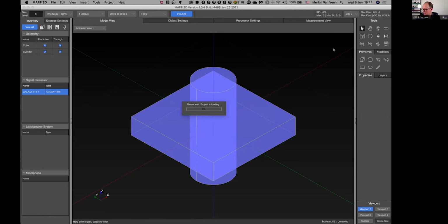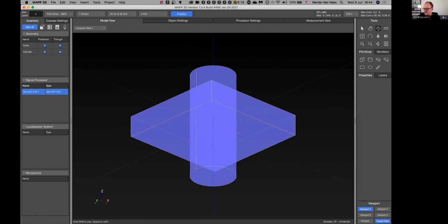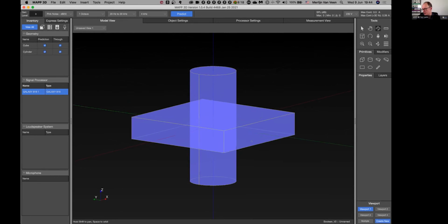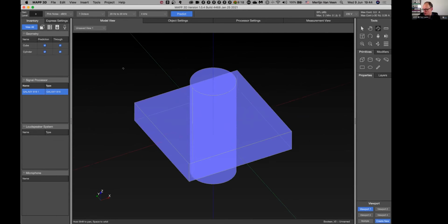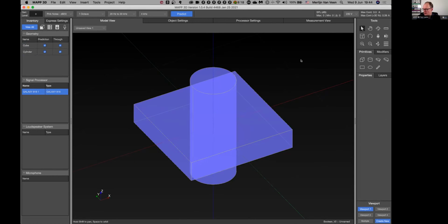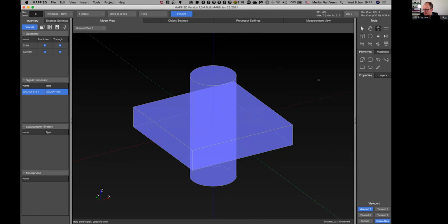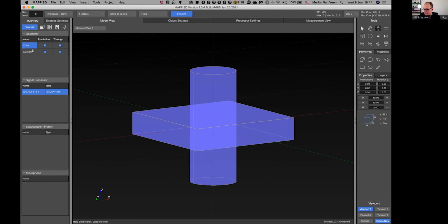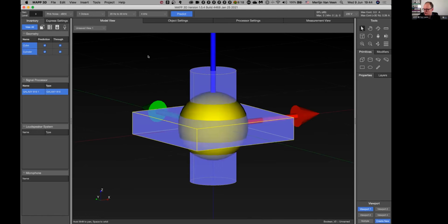Here, we're going to look at some Boolean operations, just to give you an impression of what they do. So basically, this to me resembles a nut and a bolt. Long story short, we have a cylinder, and that cylinder intersects a cube. When I select both of them, the cube and the cylinder, I can go to my modifiers and I can do union, intersect, or subtract.